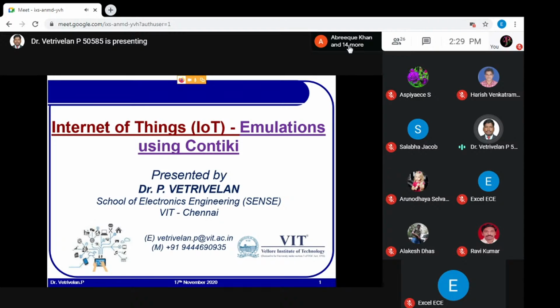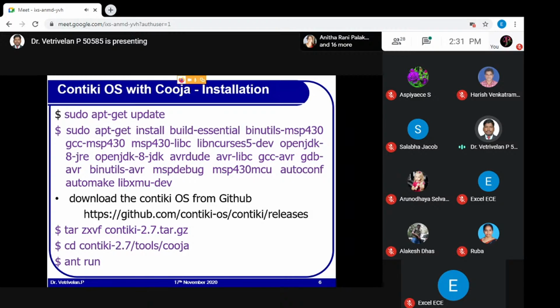If you see the protocol stack, as I was talking to you, in the sensor layer we will have solid state switches, electromagnetic switches, infrared, catalytic and photo ionization, accelerometer, gyroscope, GPS, electrochemical sensors, and an embedded controller. On top, we have a network. You may use Wi-Fi or Ethernet Shield or ultra-wideband, Zigbee, 802.15.4 with the PAN coordinator, 6LoWPAN, wired networks.